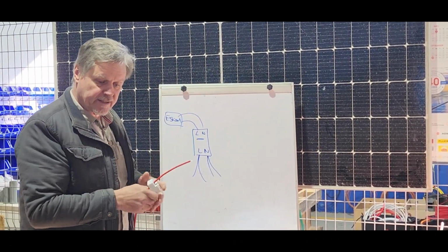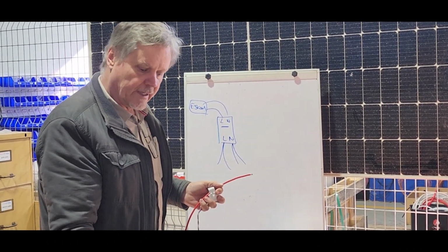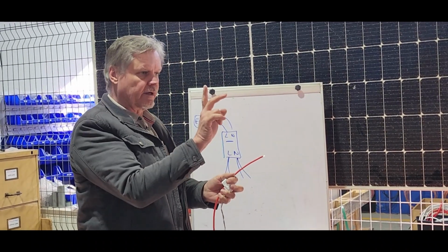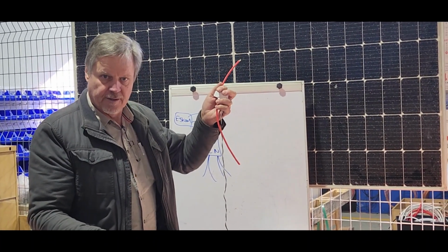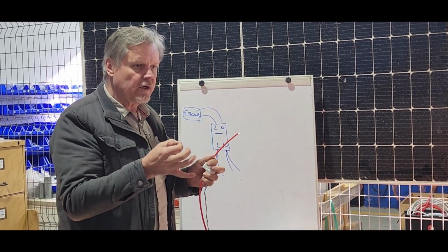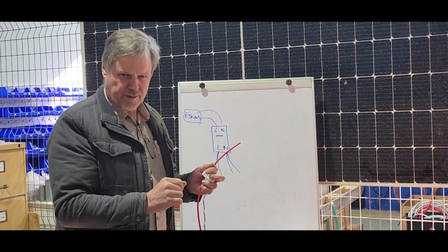Now, if you measure AC, you take an AC cord like this computer screen. Inside that cable is both the line and the neutral. So you'll measure the current going up and the current going down, and you get no output. So you must always ensure that you actually capture only one cable, the one we talked about just now. You guys okay with that?